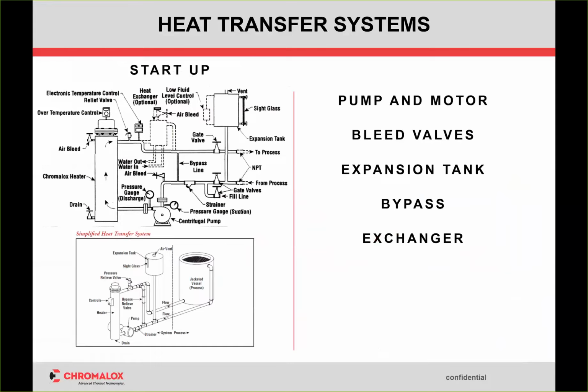A bypass line. Now, our standard larger design systems don't always have this. Our MOS does not. But it's something you want to bring up because maybe the customer hasn't considered that. Why would you have a bypass line? Well, two reasons. One, you want to keep the system up to temperature while maybe the process is being taken offline, or you're doing something else with the process altogether. Keep the system up and running at temperature.